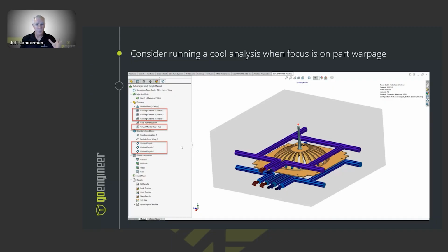If you have someone else building and designing your mold, they send you the mold design. You want to look at the cooling channel layouts and make sure that you're getting uniform cooling on your part. We can also use this to verify an existing mold that you're having quality problems or defects with. You can use that cooling layout and say, okay, this is what we're getting. Maybe I want to try a different type of cooling channel. What happens if I add bubblers or another cooling channel? Can I improve that process?